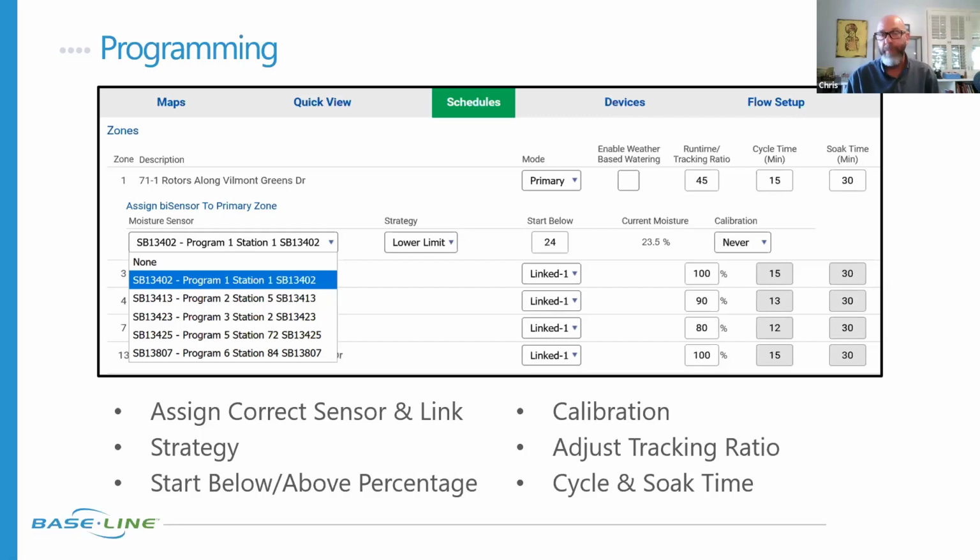So it could do it up to 90 minutes. And if it doesn't find it after that time, then it'll come back and tell you that calibration failed, and you will have to either increase your run times to try to find that capacity or go through the process again.